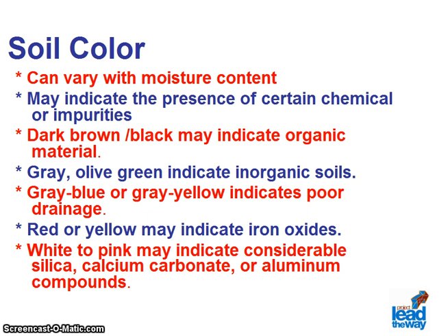Gray-blue or gray and yellow mottled colors frequently result from poor drainage. Red, yellow, and yellowish-brown colors result from the presence of iron oxides. White to pink may indicate considerable silica, calcium carbonate, or aluminum compounds.